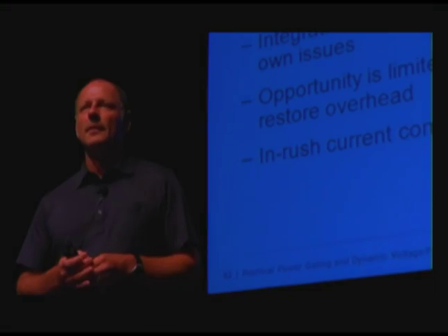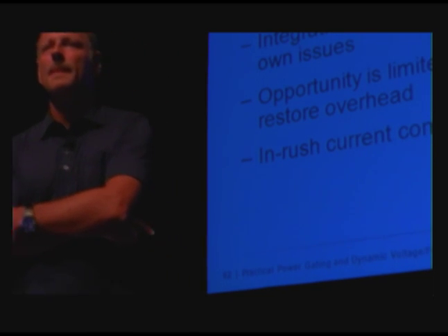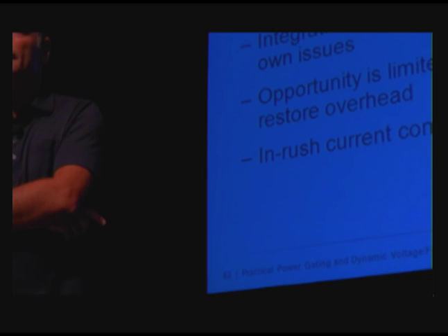So the large voltage drop component in the package is L di/dt, and so when the chip is transitioning from a very quiet state to a very high power state, like running lots of floating point unit instructions, then that di/dt is very high. So do you do some di/dt control to suppress the fast active current transition? And if you do, how do you do that without affecting the performance?